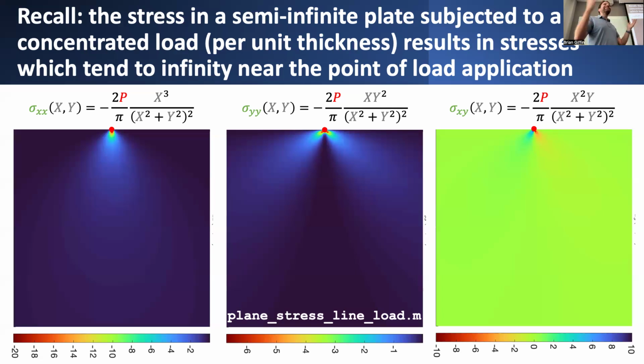Even though the theory of elasticity gives us the tools to be able to come up with solutions like this, sometimes they're not always reflective of the physical reality. And that's really the takeaway that I want you to have from this problem. There are technically two issues with the fact that the stress goes off to infinity in this problem.